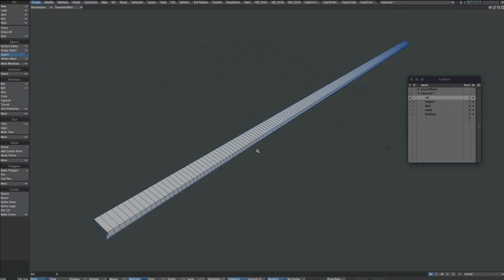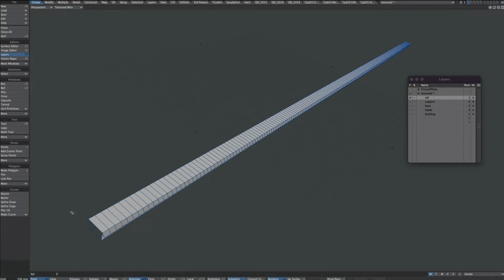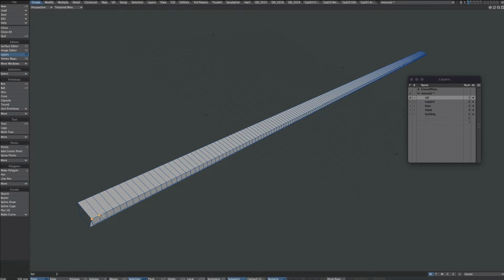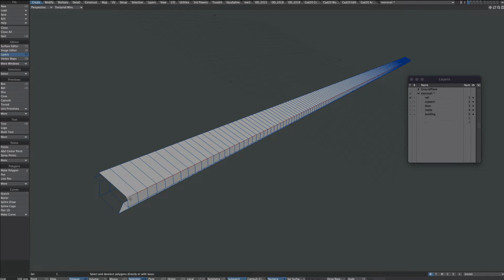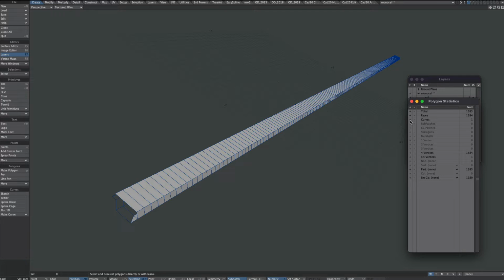We could easily rig this in Layout, but I think there's a quick enough technique to do in Modeler, which I'm going to show. So let's select the first 2 points. Right arrow key to select the remaining points along this edge, and Control P to create a spline. There it is in the menu. There it is selected. We'll cut it to detach it from its points and then paste, and it should still be selected. If it isn't, press W and select curve there.